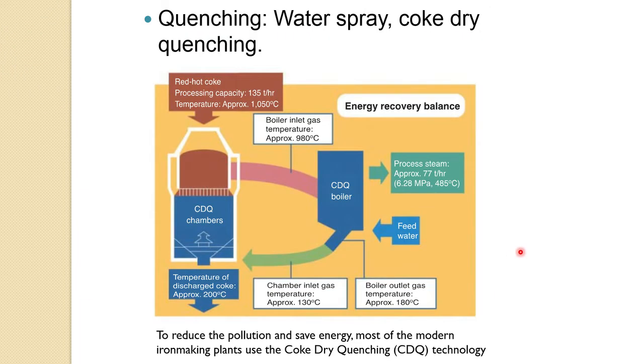Quenching could be wet or dry: either water spray or coke dry quenching. Water spray is not environmentally friendly; it used to be done like this, but it generates lots of dust and other things. A new quenching technology has come, called the coke dry quenching, or CDQ, technology.